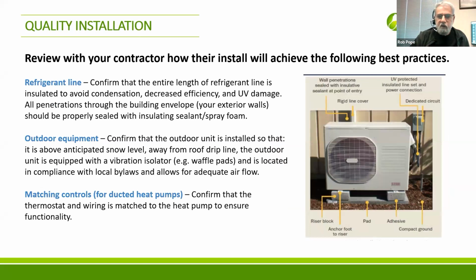Just like we talked about, for the actual installation, good practice is to make sure that the entire length of the refrigerant line is insulated. That's pretty critical, from beginning to end. And all penetrations through the building envelope, through your exterior wall from outside to inside or vice versa, are sealed properly. Those are two sets of issues that I see a lot that haven't been adequately done in the field.